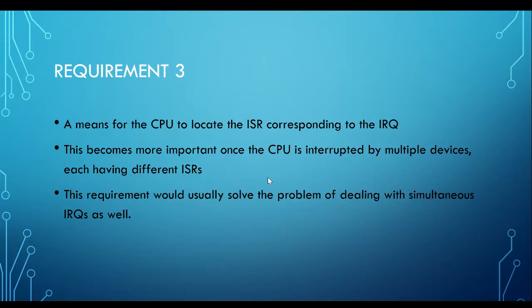The CPU has to locate the ISR corresponding to the IRQ. If you define pin 2 as an interrupt for this, do this. I had a project once that used interrupts, and because it was not very stable, I decided to use polling instead. I generally find that for Arduino, using interrupts has a bit of a problem, probably because of power issues or something like that. So if the interrupt is not very stable in your project, go back to polling. The polling concept is normally more stable, but power consumption is slightly higher.